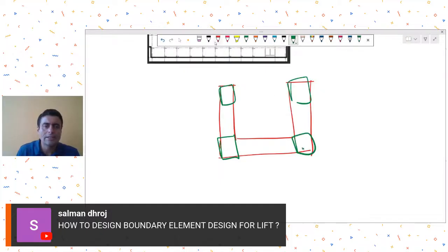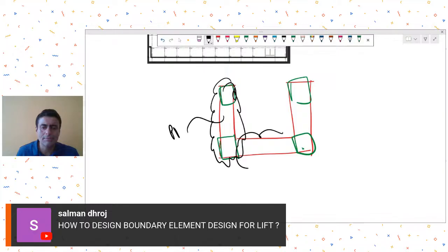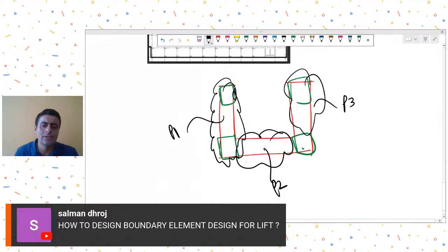And as we have discussed this point before also, if you have made this type of wall in ETABS, let's say, you first of all assign separate pier labels to them, analyze it, design it. Once you analyze it, you will get the pier forces.